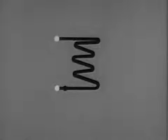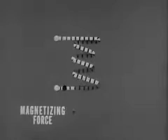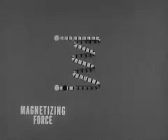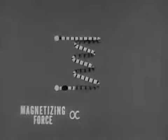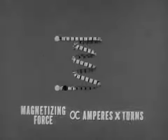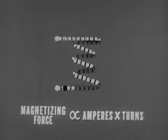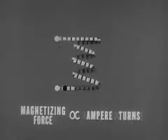Any winding around the core obeys the laws of electromagnetism. The magnetizing force it exerts is proportional to the amount of current flowing through it measured in amperes times the number of turns in the coil. Or, as it is usually expressed, the ampere turns.